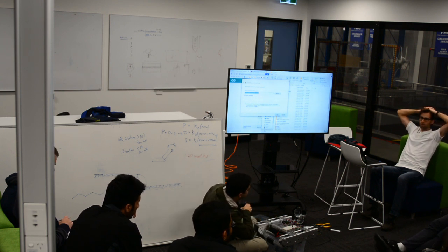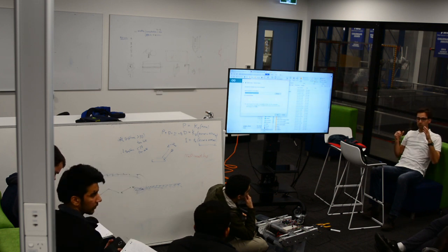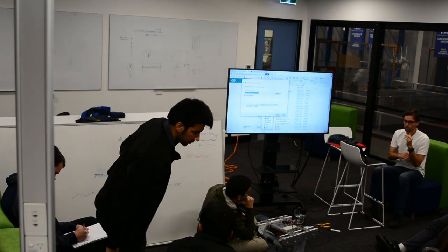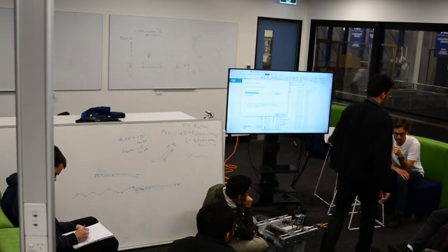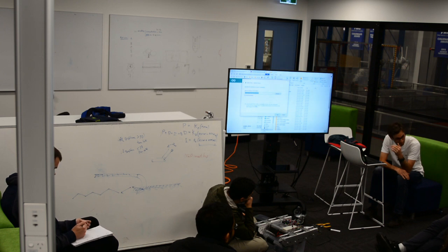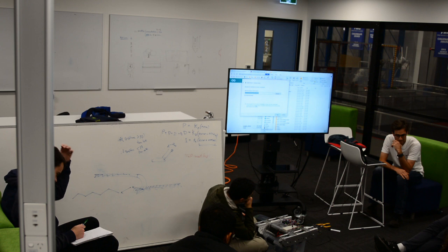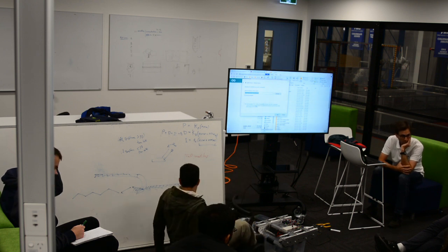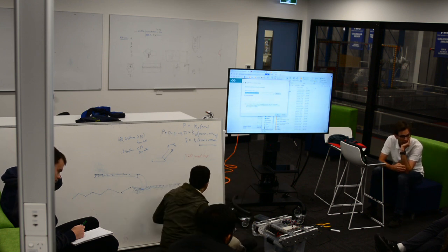Is that going to make a big difference though? Because I suppose you don't want the cans flying everywhere. Yeah. Plus, if you want to go to a position and then stop, you could also have a tight control system but limit the total speed. So we could still have a high proportional gain, but not achieve max throttle. That might help a little bit. The other option is sending it regular updates to position so that you can decelerate it as it comes in by sending it a move profile, essentially.